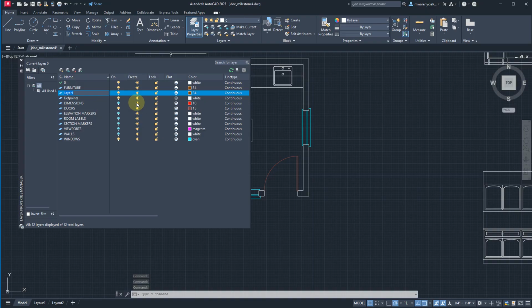So if we were doing the full boat, like AIA, American Institute of Architects, or US National CAD standards, the right way to do this, for example, the Casework would be A. So you would indicate what your base architecture layer would be. So this would be architectural A. And then we would do dash casework, which is a fancy word for cabinets. And then we would have a base layer for casework, right?